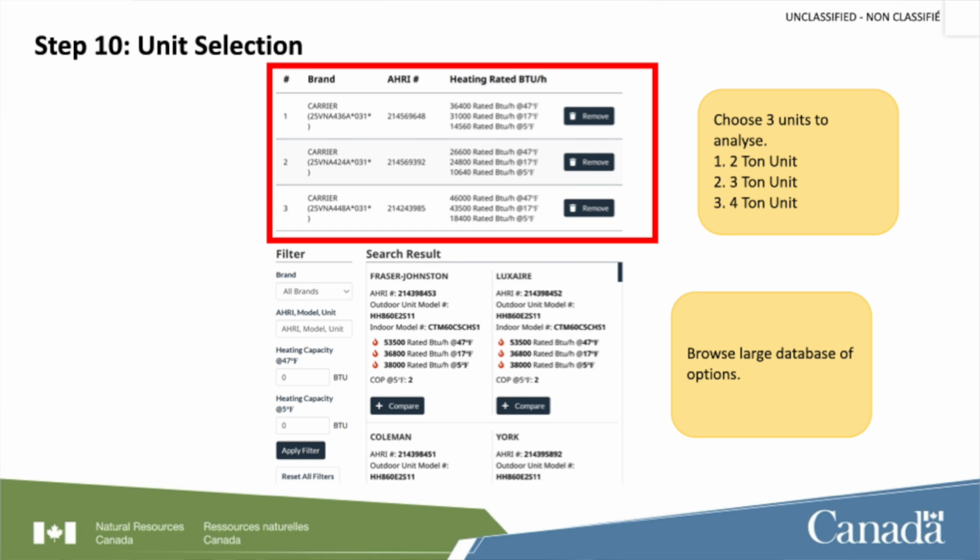If I have any advice to give anybody on this, it's don't try to mix and match too many things. If you have a Carrier exterior unit, please use an interior coil from Carrier as well. The one notable exception is ADP. ADP does have some testing with other manufacturers, but it's kind of a go-with-God-and-pray situation. But if you're sticking with Carrier, Trane, Tassat, Daikin, all the usual suspects, chances are these guys are in the database, and this will give you that good information that you require.